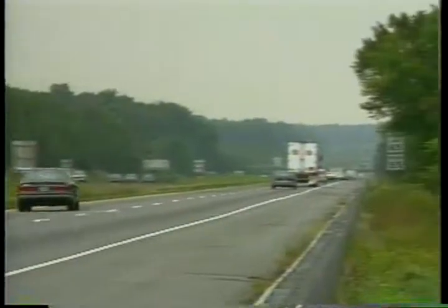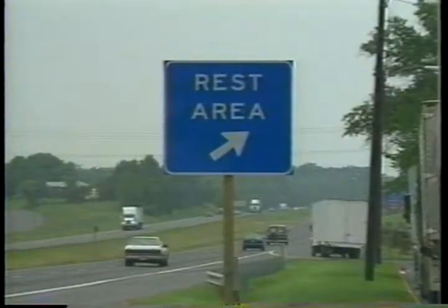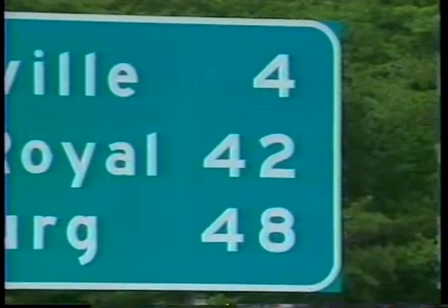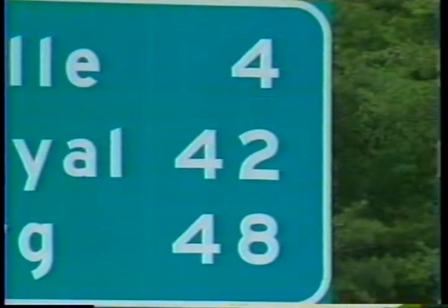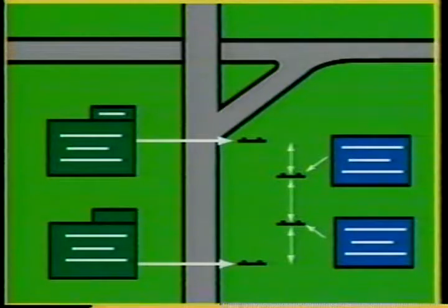Between interchanges or in non-interchange areas, there are route markers, rest area signs, and distance signs. Normally, distances to the same destination should not be shown at less than 0.8 kilometer intervals. Motorist service signs should be located 250 meters from an interchange. They should never obstruct the view of other traffic control devices. These signs should be at least 250 meters apart and 250 meters from other traffic control devices.